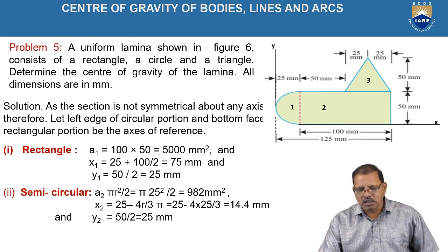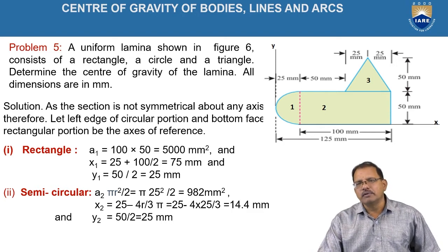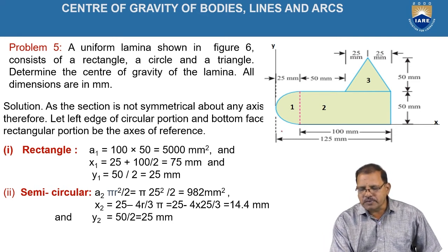according to engineering mechanics, the regular figure is nothing but a triangle, rectangle, square, circle, or semicircle. Hence, it may be a combination now, but here this figure is treated as an irregular figure. For this, in order to determine the center of gravity of this figure, let us consider the line passing through the bottom of the figure. It is treated as the x-axis. The extreme left position is treated as the y-axis.